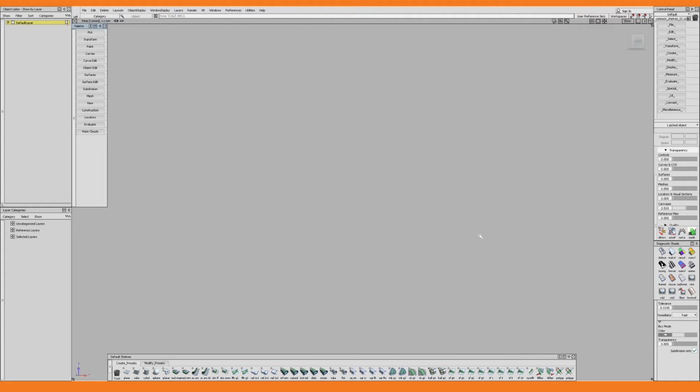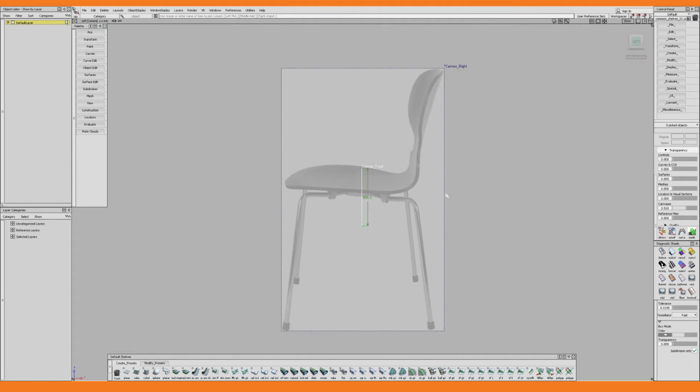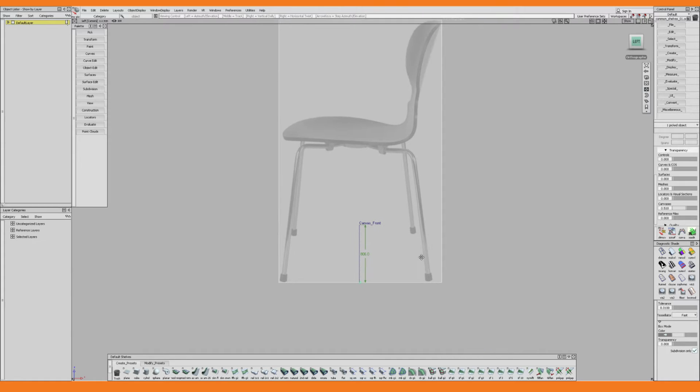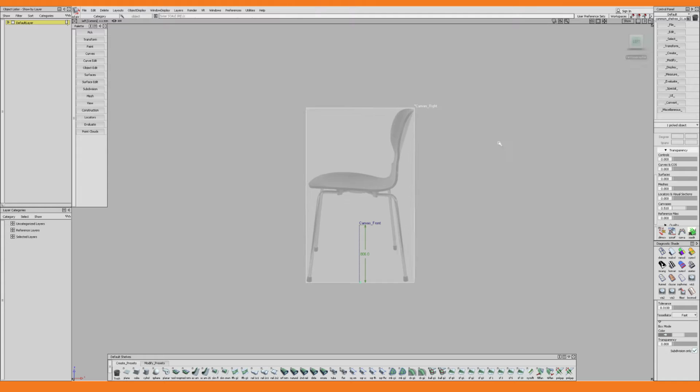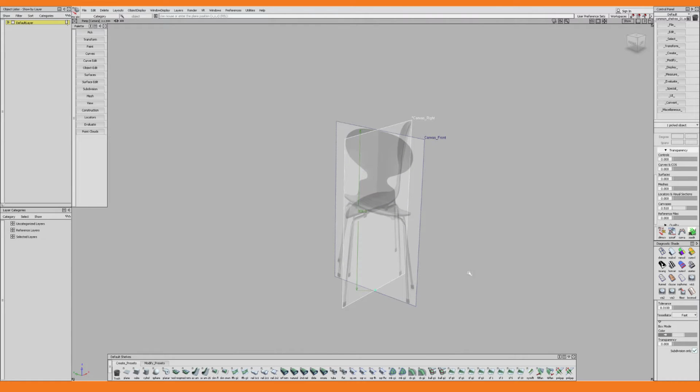And then let's switch over to the side view to repeat the process. So I once again import the image, then I snap the pivot to the bottom, and I align the canvas image to the grid before scaling it until it matches with the distance locator and our front view image. And now I want to move it a little bit to the side so it's out of the way, and the same goes for the front view.